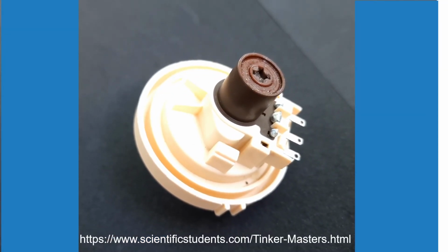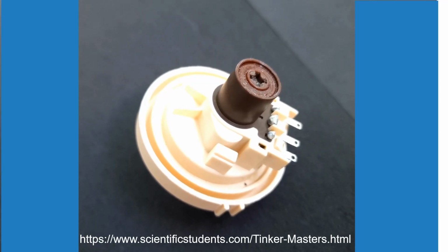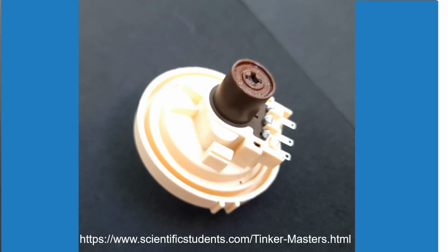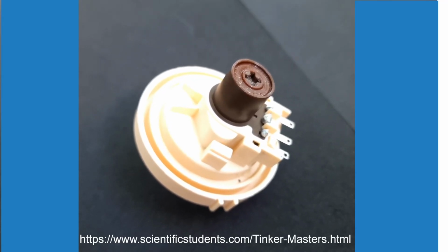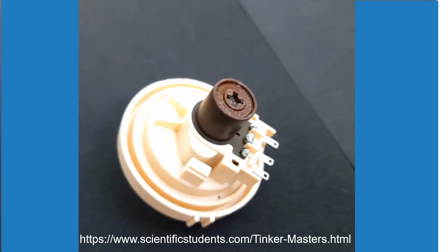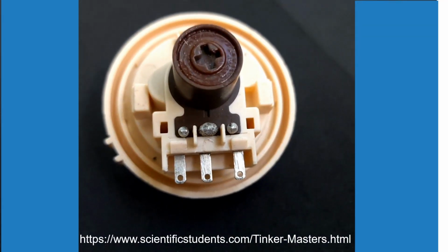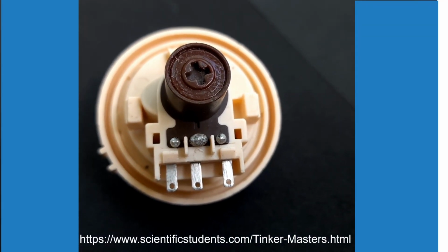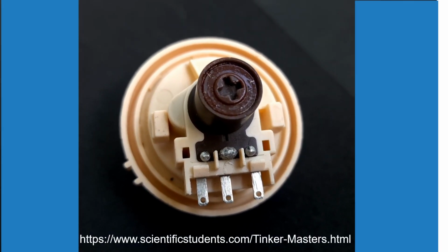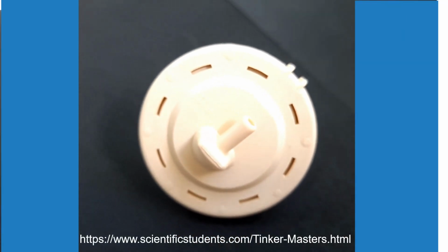My dear students, as I have explained about restoring my LG 6.2 kg washing machine, we found the culprit. This is the pressure sensor. There are electrical connections, and we found a lot of dust on them. So we have cleaned them very nicely now, so that the signal will go properly to the microprocessor, the control unit.